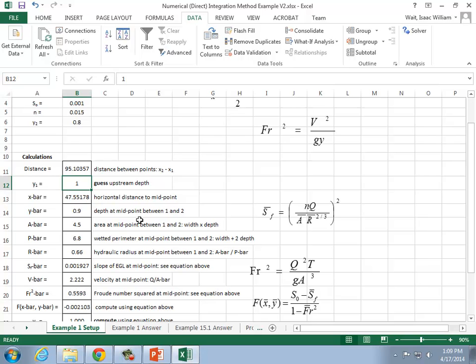We talked about that in our last class lecture. But what I'd like you to do in part A is find out how far it is downstream to where the depth will be equal to 0.55. So we know that right after the gate, y1 is 0.25 meters, and y2 is 0.55 meters.